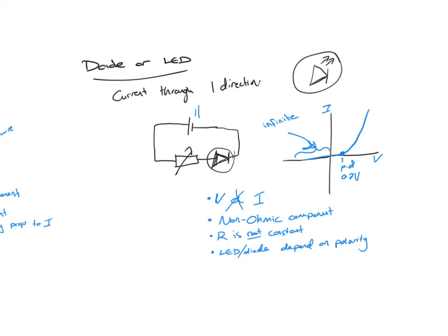As potential difference increases, the current increases, which means that if current increases, the resistance decreases because it allows more current through. We said already, the higher the resistance, the lower the current. So the resistance actually drops extremely fast for very small increases in potential difference, and we say that at this point it has little resistance, because the current increases very sharply.